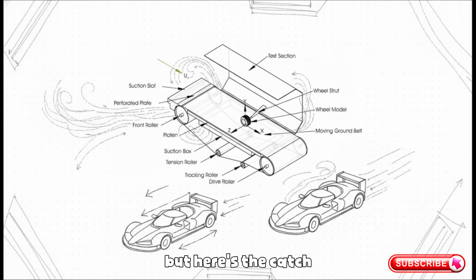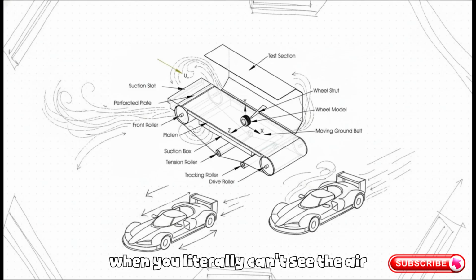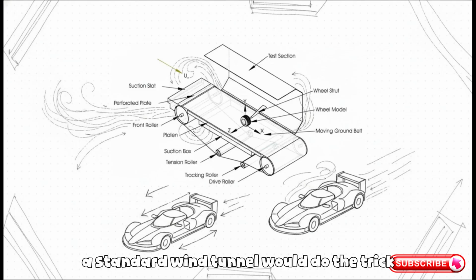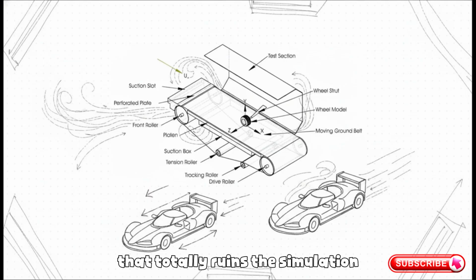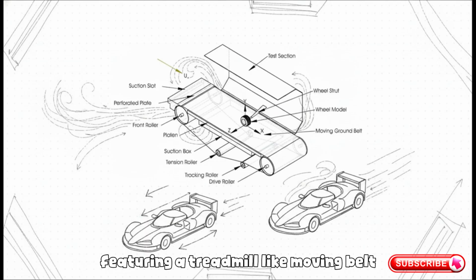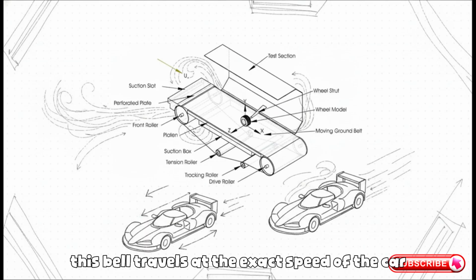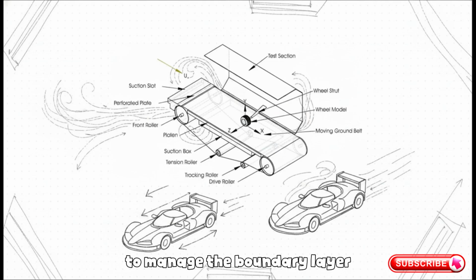Moving to Section 3, testing invisible aerodynamic forces, making the invisible visible. But here's the catch. How do you study this highly complex physics when you literally can't see the air? You might think a standard wind tunnel would do the trick, but traditional fixed floors create unnatural friction that totally ruins the simulation. Instead, researchers have to use highly complex setups featuring a treadmill-like moving belt. This belt travels at the exact speed of the car to correctly simulate the ground moving underneath it, complete with suction slots to manage the boundary layer.